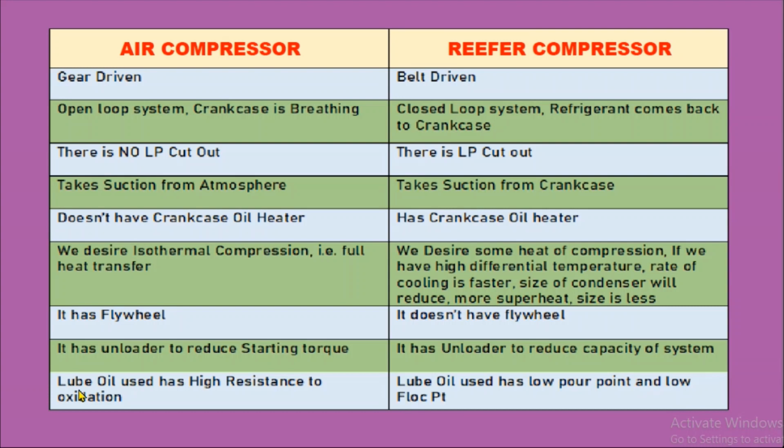Lastly, the lube oil used in the air compressor has high resistance to oxidation, whereas the reefer compressor lube oil has a low pour point and low flock point. So these are some of the points which can differentiate between the air compressor and the reefer compressor on board.